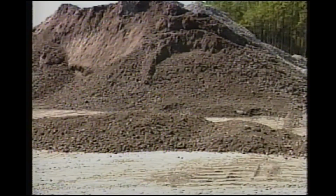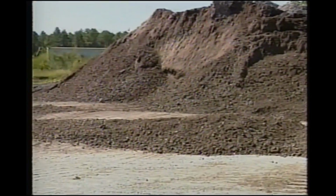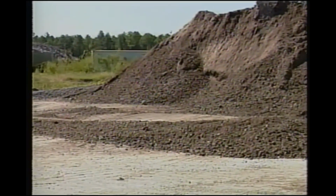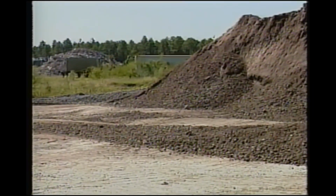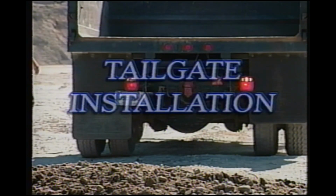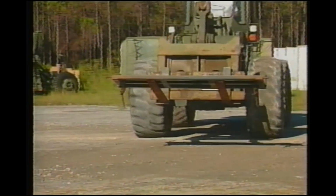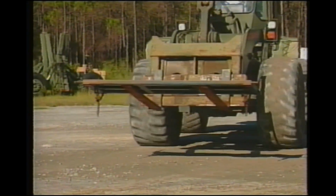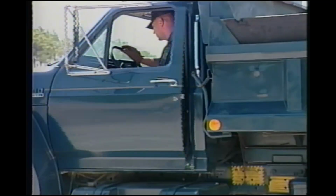Spreading material with the tailgate removed is ideal for bulky items, wet sticky material, areas requiring thicker lifts, and small areas. This method permits faster discharge of material. The tailgate is too heavy to try to manhandle. Reinstallation is a lot easier and safer if you use a forklift.